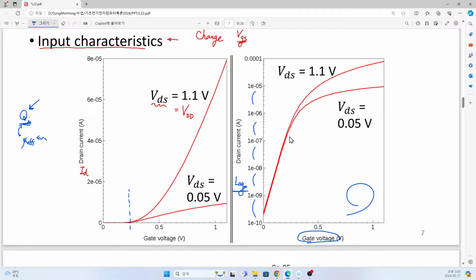So in this case, now you can see in this part, even below a certain gate voltage, we feel that when the gate voltage is lower than a certain value, the threshold voltage, then maybe the current conduction is not allowed because we don't have enough electron density. Yes, we don't have enough electron density, but we have electrons there. So this small amount of electrons actually conducts a small amount of current.